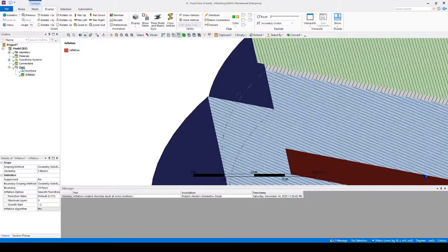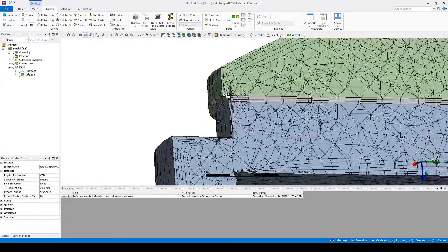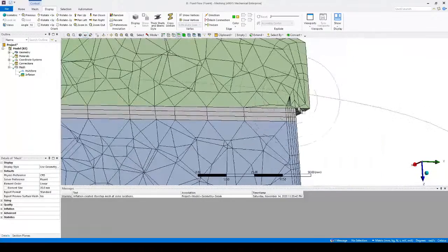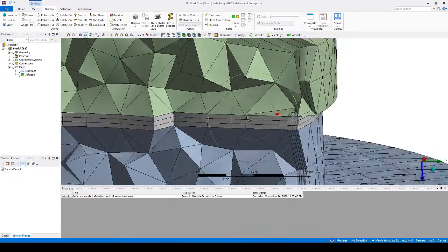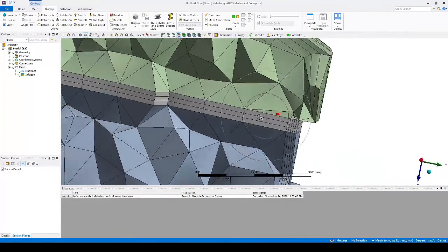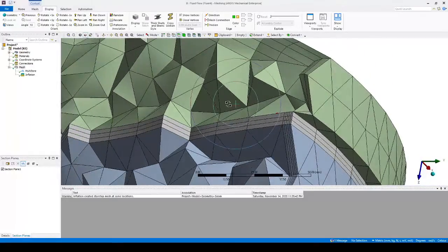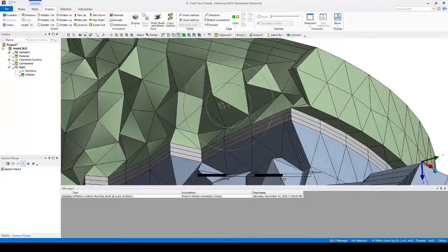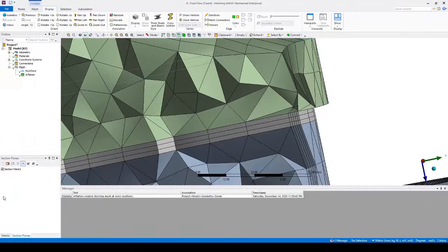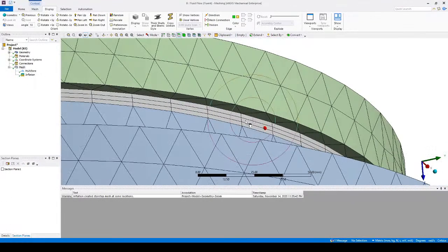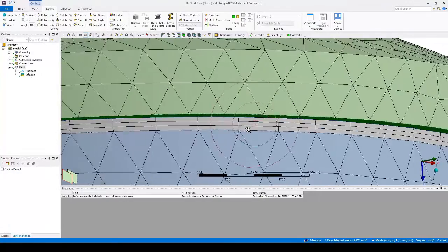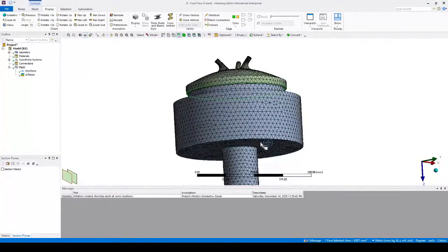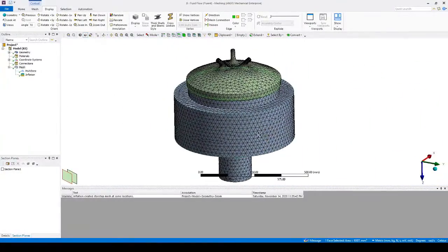Got that surface. This mesh doesn't look great over here, I have to say. I think this surface turn was a little bit too spiky. Yeah, somehow that does not look all that great. Yeah, I think we probably should refine the mesh over here to get a better solution, so that we may have some convergence issues in this.